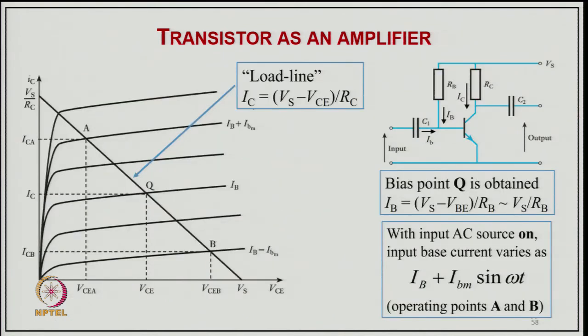And here, of course, we can say the load line corresponding to IC equals (Vs minus Vc) by Rc, and that is typically the load line of this collector current and the collector-emitter voltage in this circuit. So, the bias quiescent point will correspond to almost DC only on this point. So, IB will be (Vs minus Vb) upon Rb, that is the biasing we are providing from the bias resistance from the supply voltage, because the voltage drop corresponding to the base-to-emitter junction is very small.